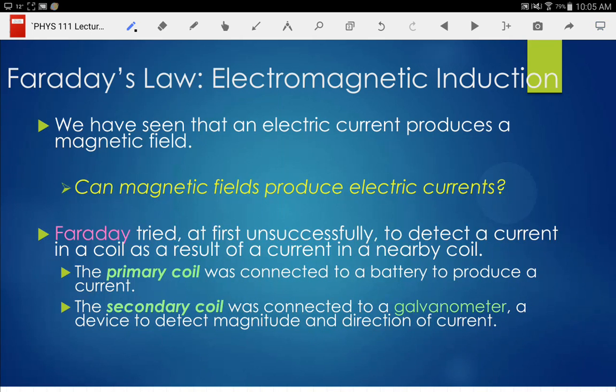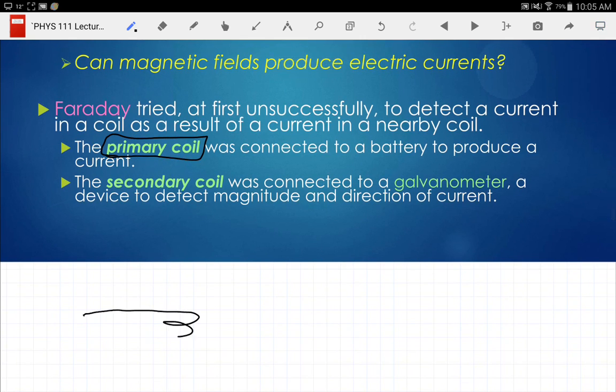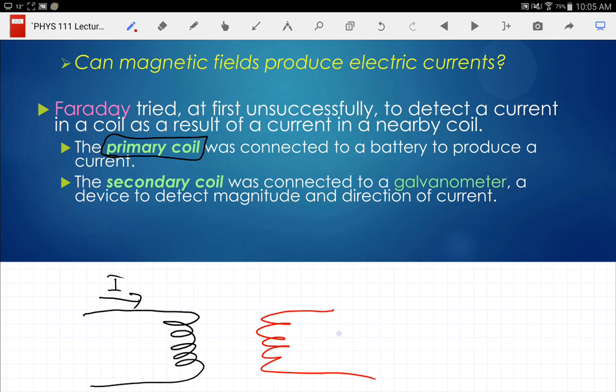Getting on to transformers. Everybody knows what a transformer is. It's more than meets the eye, right? It's not a robot in disguise, though. A transformer, as we use in electricity, is a device that uses 2 coils that are coupled together. So we have one that's called the primary coil. And so you have electric current that comes and goes through that primary coil. And then we have a second coil that's called the secondary coil. And there's no electrical connection between those 2 coils.